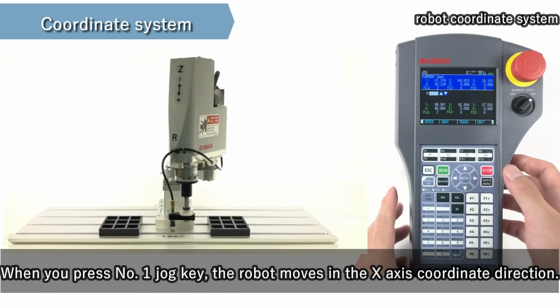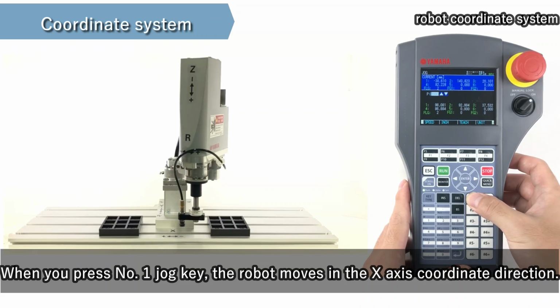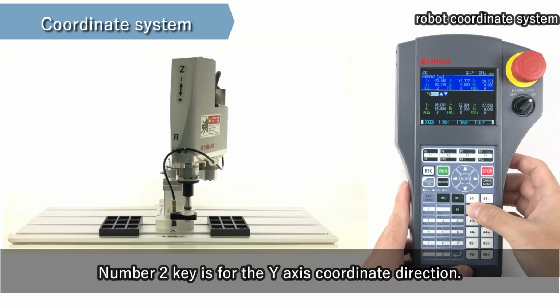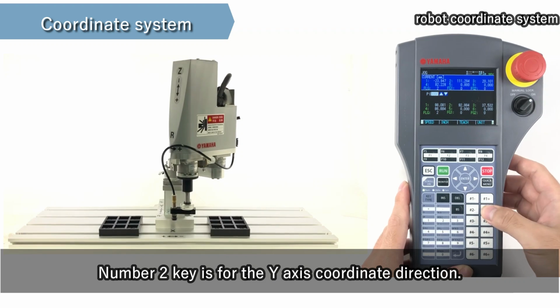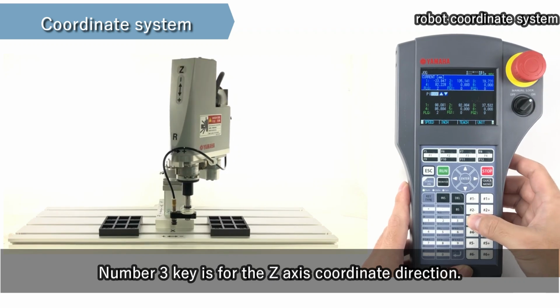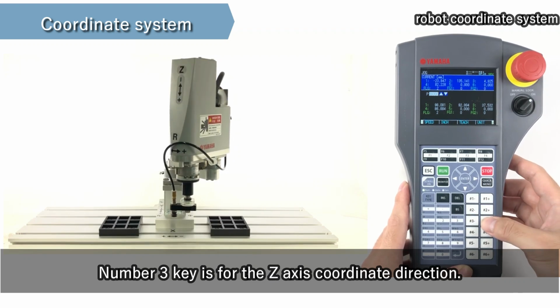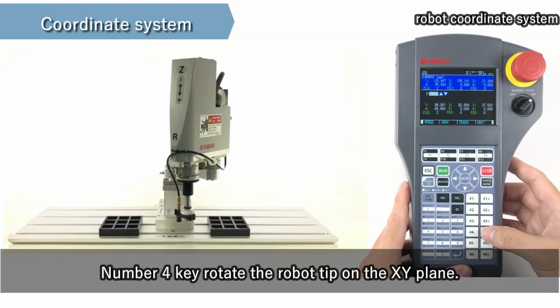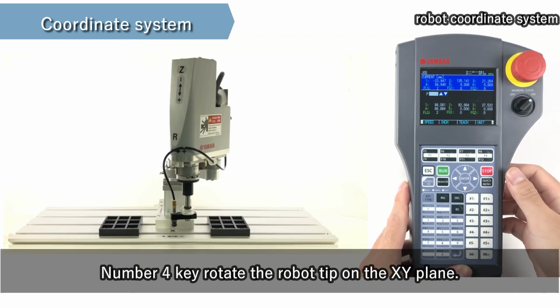When you press number 1 jog key, the robot moves in the x-axis coordinate direction. Number 2 key is for the y-axis coordinate direction. Number 3 key is for the z-axis coordinate direction. Number 4 key rotates the robot tip on the xy plane.